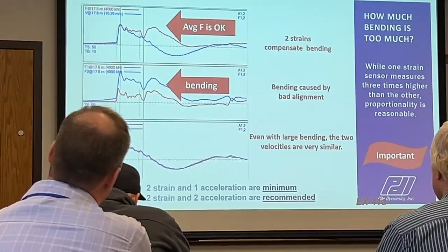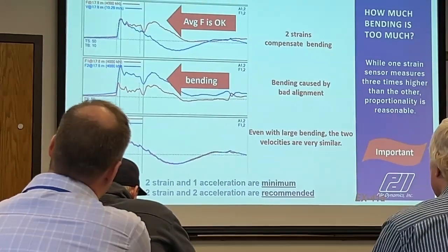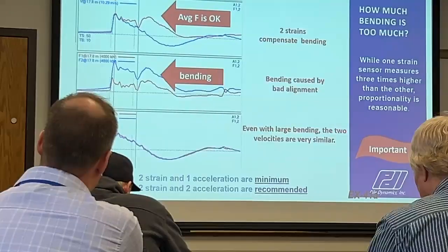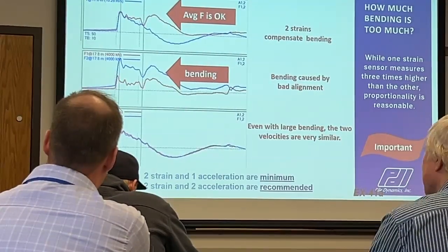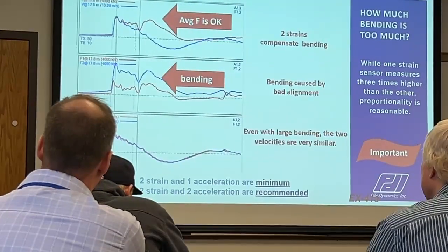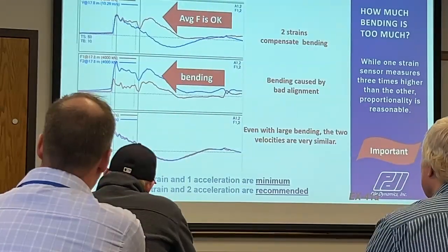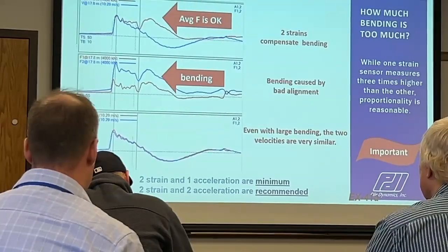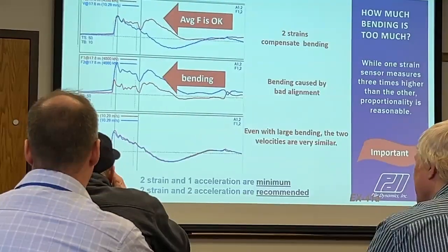So, one time, in my misspent youth, I was out taking data, and I saw this, and my training kicked in, and I said, that hammer is not well aligned, and in fact, I can see it. So I told the contractor that maybe he should boom out a little so the hammer became more vertical.